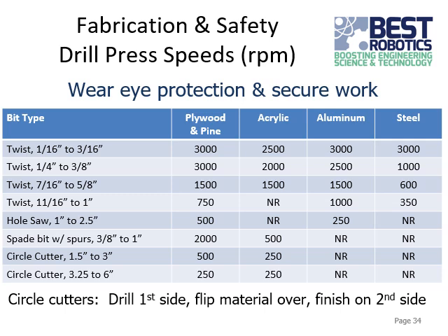The other thing here that's not really mentioned is that with some metals, at least with the harder metals like steel, you're going to want to use some sort of cutting fluid. That's basically a little lubricant that will keep the drill bit cool and keep it from overheating and deforming.